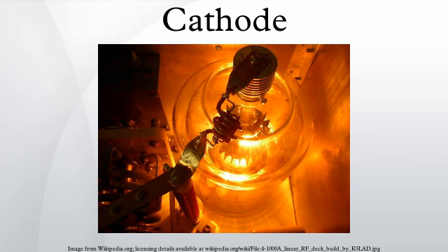In order to improve electron emission, cathodes are treated with chemicals, usually compounds of metals with a low work function. Treated cathodes require less surface area, lower temperatures and less power to supply the same cathode current. The untreated tungsten filaments used in early tubes had to be heated to 2500 degrees Fahrenheit, white hot, to produce sufficient thermionic emission for use, while modern coated cathodes produce far more electrons at a given temperature, so they only have to be heated to 800-1100 degrees Fahrenheit.